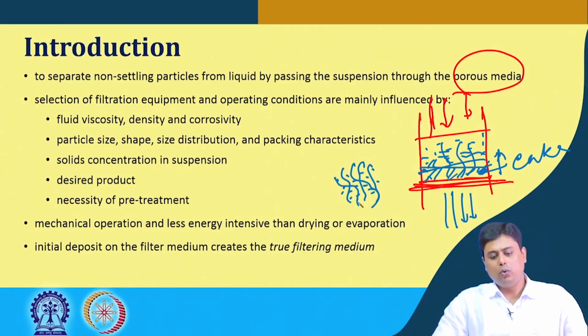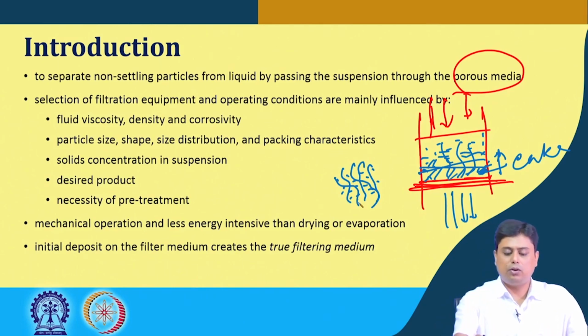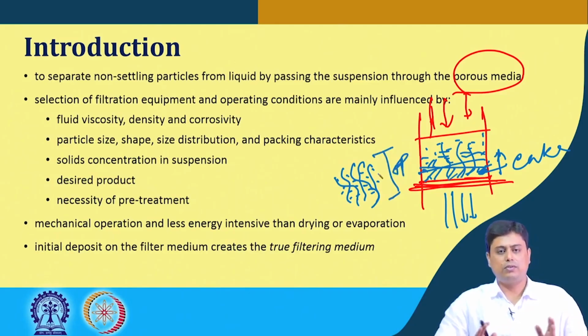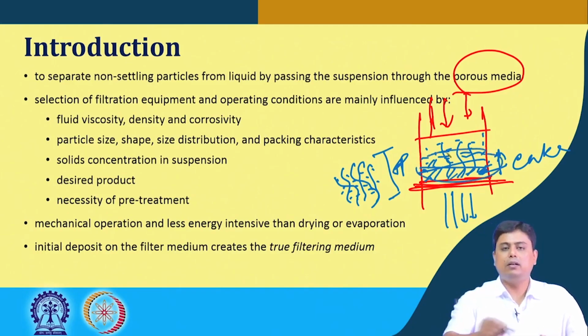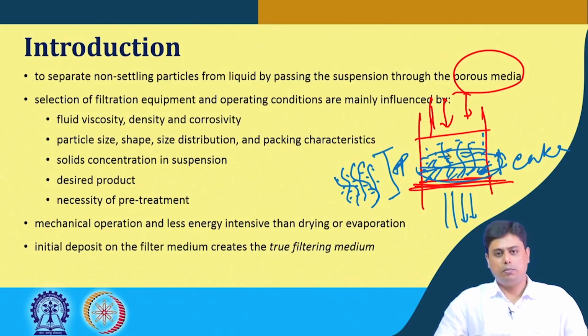We already have known what would be the pressure drop in such cases. We have seen Darcy's law, we have seen the Ergun equation, we have seen the Kozeny-Carman equation. So, a similar concept can be applied here, where the effective media is the cake medium, which is of solid particles, the porous material. We call this porous media, so, flow through porous media.